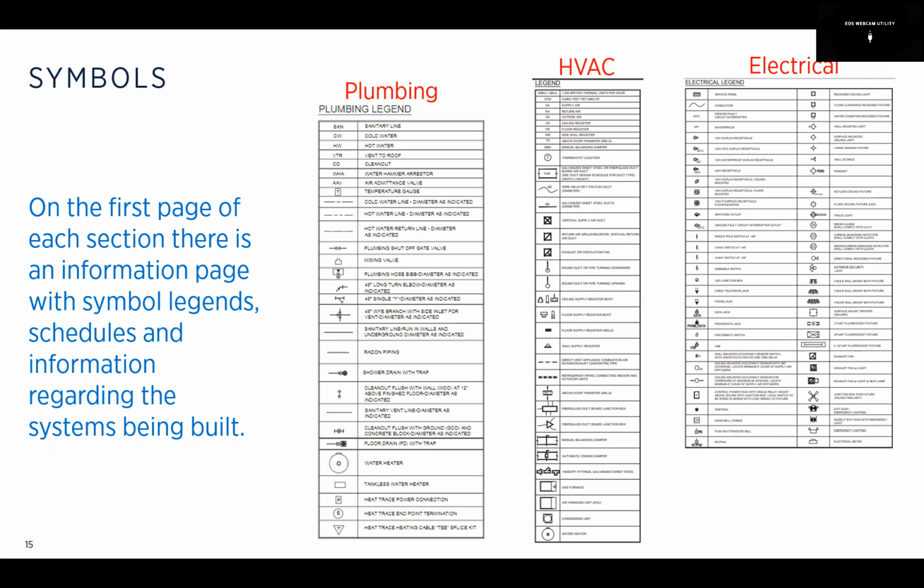Okay, got it. It's very important to understand when you're doing your plan review whether your diffusers are in the ceiling or on the floor. So you can quickly look at the diagram and say, oh, okay, I get it. That's in the ceiling, or nope, that's in the floor, because that's going to affect cabinets and things like that. Or if it's a decorated model or a decorated building, it's going to affect furniture layout. Anyway, so it's very important to be familiar with the symbols.